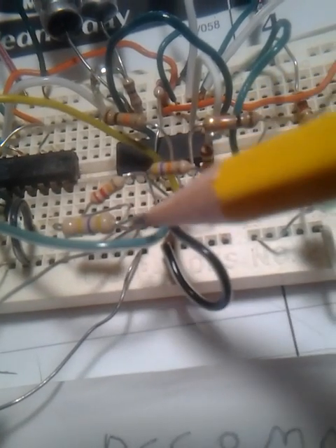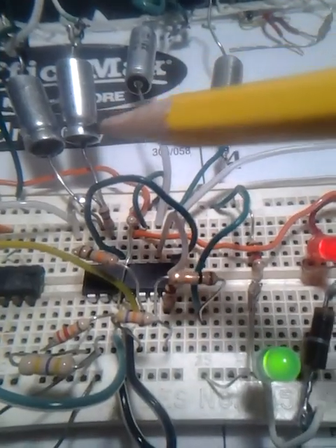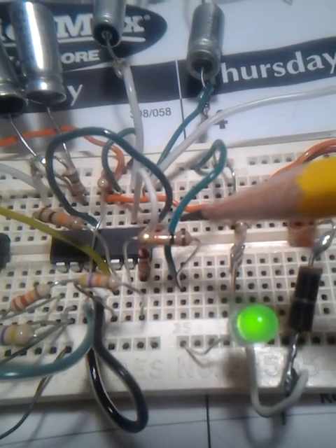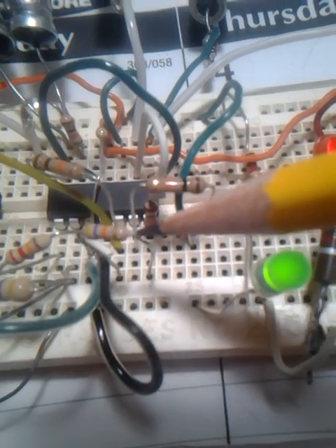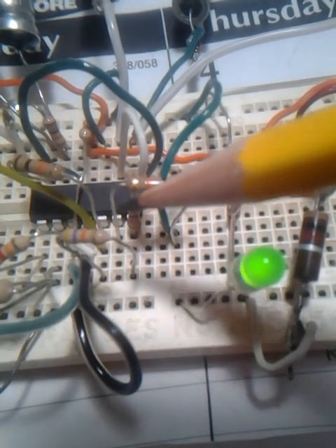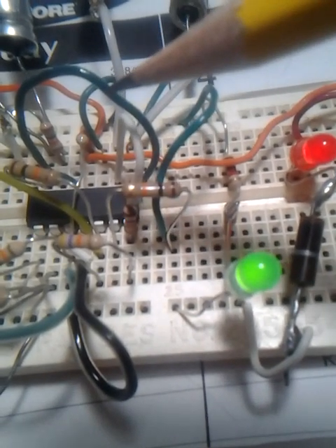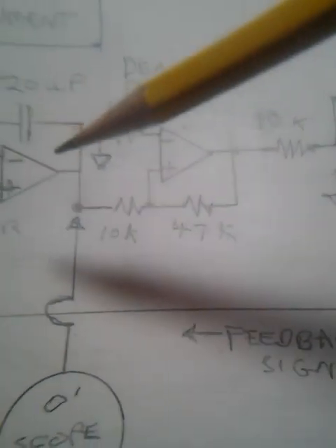About a 3 microfarad capacitor, impulse circuit, a signal circuit. So that's where you get the signal. The output is 2 capacitors, which I show on the schematic, 10K resistors, and a 10K resistor going down to the hysteresis circuit, which consists of a 47K resistor and a 10K resistor, the output being fed back as shown on the schematic. And here is that circuit.